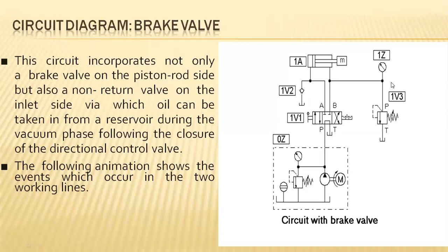So this is the basic condition where the pressure relief valve plays a major role, in that it acts as a safe pressure for movement of the piston in the forward stroke, limiting its motion by imparting pressure constraints, and also in the backward direction by positioning this non-return valve or check valve here, operating with the safety pressure of this pressure relief valve in the return direction.